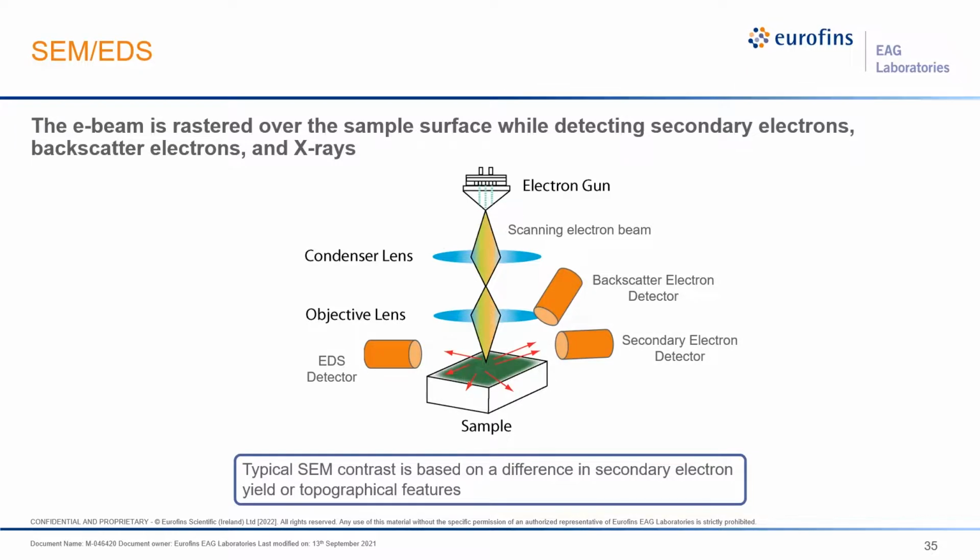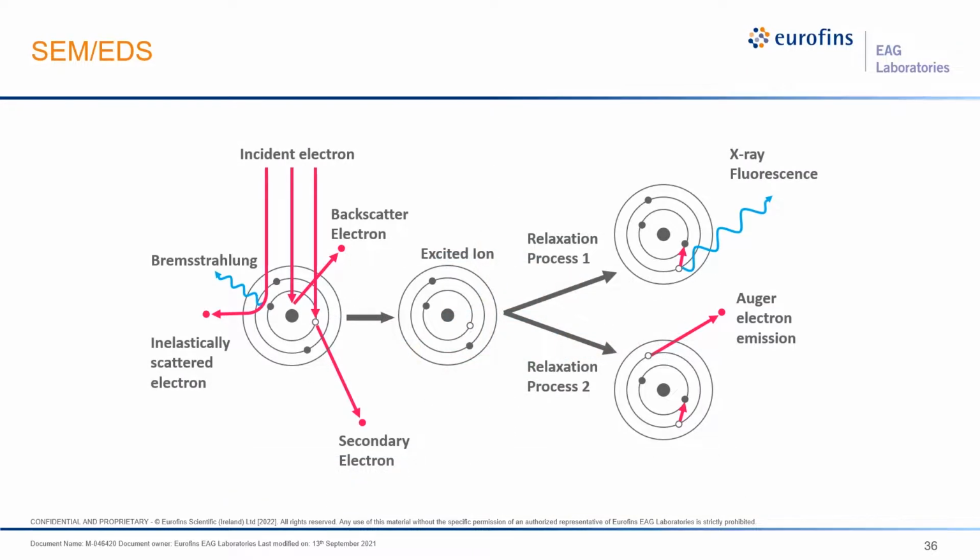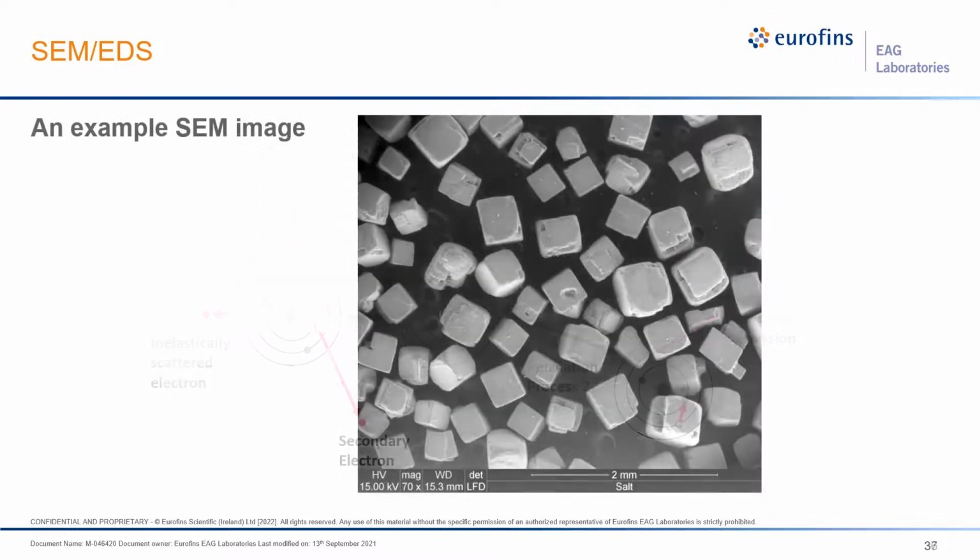That's our friend here. How EDX gets the X-ray, I'm not going into too much detail, I'm going to fly through these. When the E-beam comes in, you get an excited ion because a secondary electron is removed from the inner layer. The relaxation of an outer layer electron going in is what leads to the X-ray fluorescence. That's the signal we're detecting that leads to our elemental information.